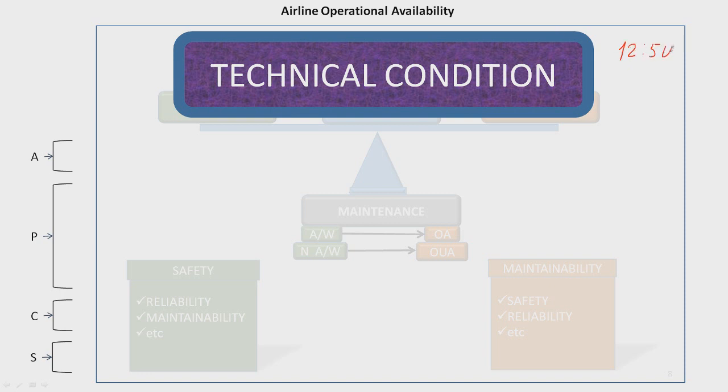Okay, and the mechanic comes, let's say 12:45, to control engine start from the ground. So the mechanic tells the pilot, okay, we can start engine number 2. Pilot starts engine number 2, connects AC generator. Then the mechanic moves to the left side, and says, okay, everything is clear to start engine number 1.